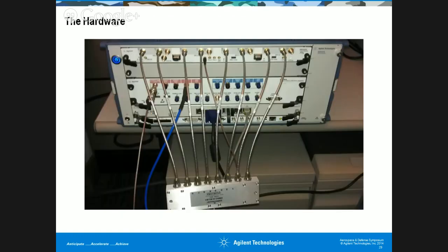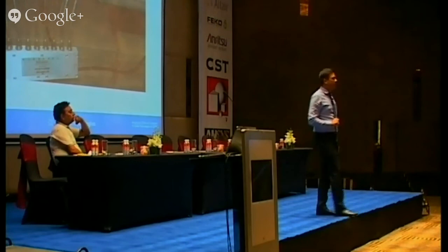So this is a picture of the hardware shown here, wherein we have these 8 channels, and what we are showcasing here is that we are feeding one single-tone signal, dividing it through this 8-channel divider and feeding it in for calibration purposes. All these cables are phase-matched cables, and then we are calibrating this particular system, and after calibration, as I mentioned, we are able to achieve up to 30 picoseconds of inter-channel skew, which is around 3.5 degrees at 300 megahertz.